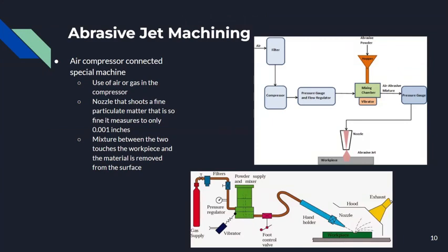These minerals are introduced into a mixing chamber where they are combined with high pressure air obtained from a compressor. A vibrating bottom at the base will help the chamber to mix the air and particles thoroughly. Then once mixed, the two will be transported via a line to a nozzle. And then in order to create the blasting process, Bernoulli's formula will have to be used. This means that as the pressure decreases when leaving the nozzle, the velocity of the mixture will have to drastically increase. This high velocity abrasive will then hit the work material and begin to blast away any unwanted pieces or material through friction. Once this process is finished, the manufacturer will be left with a smooth finished piece.